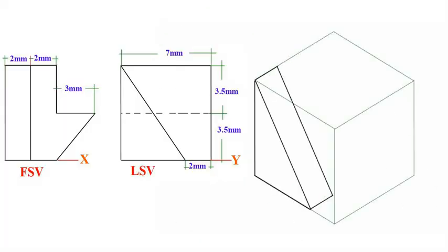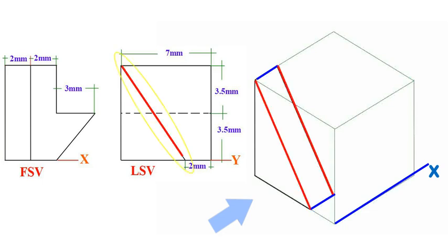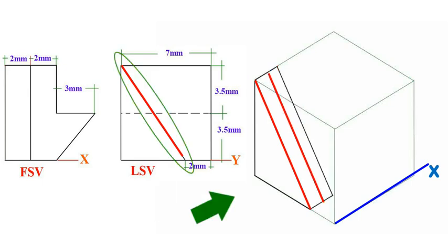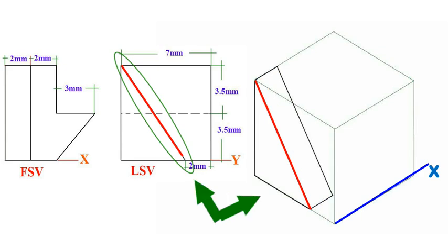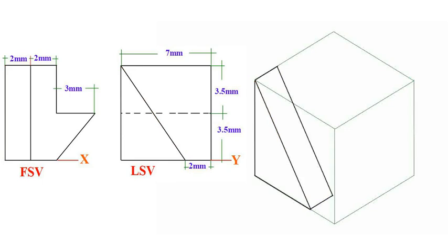As previously mentioned, the x-axis line is not visible from the left side view. The inclined plane is drawn using both the x-axis line and the inclined line. When the x-axis line is removed since it is perpendicular to the left side view, the resulting view takes this form. Consequently, the shape to be drawn from the left side view is the upper rectangular-like figure.